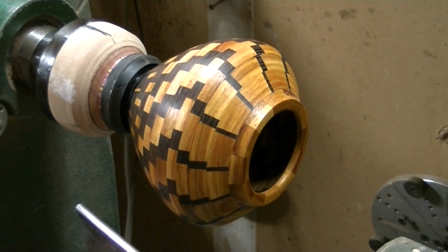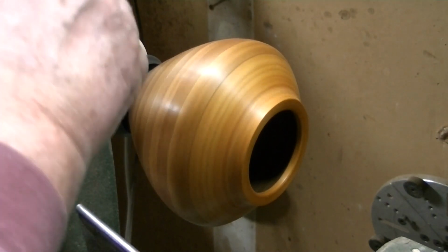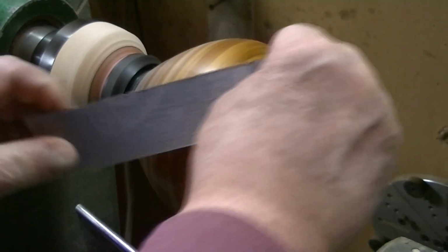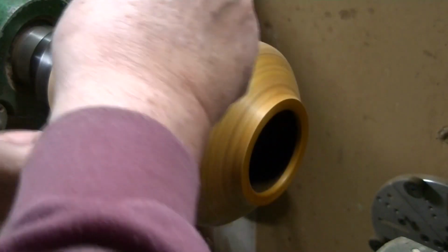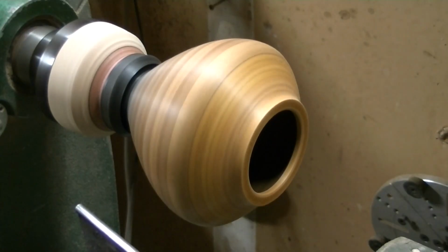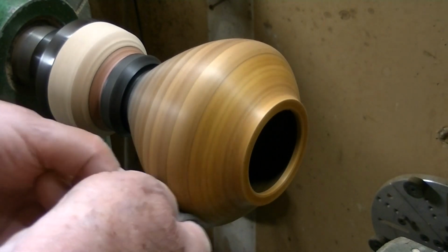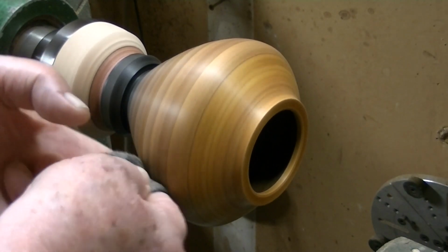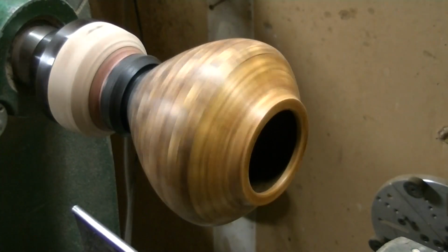Well, after that dries, it goes back onto the lathe again. And I'm going to take my 120 grit, 180 grit, 220 grit sandpaper and sand this back down to the surface again. What I'm doing is allowing the finish to fill into the pores of the wood and establish a flat base. So we need to do more sanding. Sometimes we don't want to, but we do. I'm finishing up here with a piece of 4/0 steel wool simply to give a really nice surface finish. I'm going to do this about 5 times.